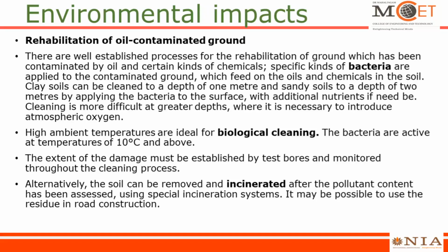The extent of the damage must be established by test bores and monitored throughout the cleaning process. Alternatively, the soil can be removed and incinerated after the pollutant content has been assessed, using special incineration systems. That is, you are burning them. Right? It may be possible to use the residue in road construction projects.